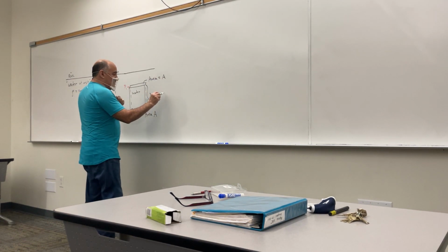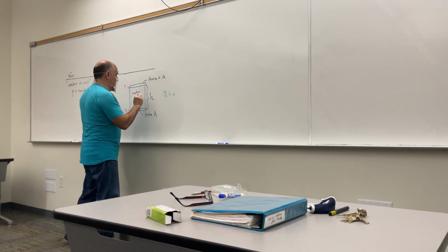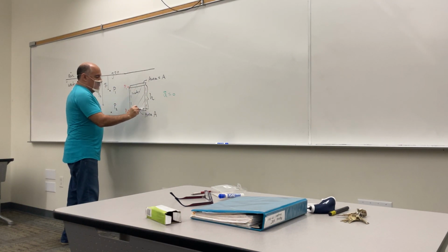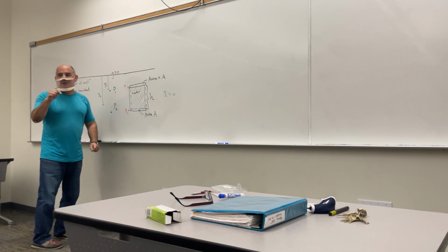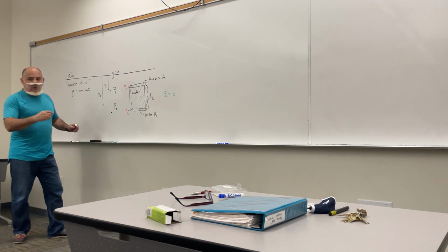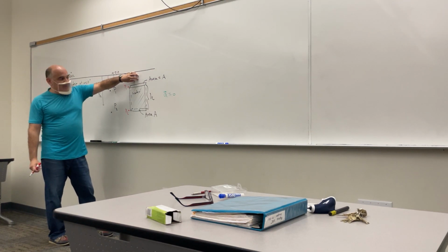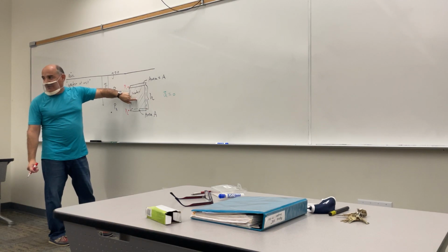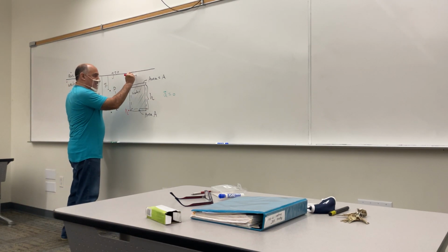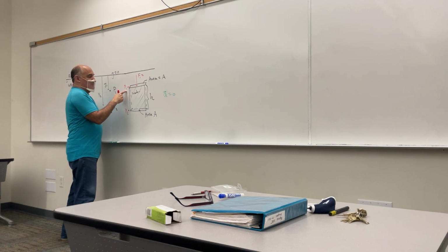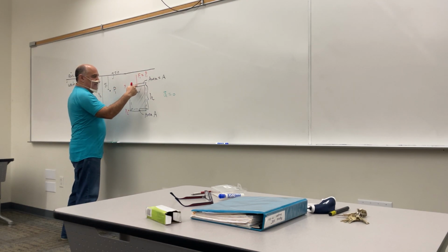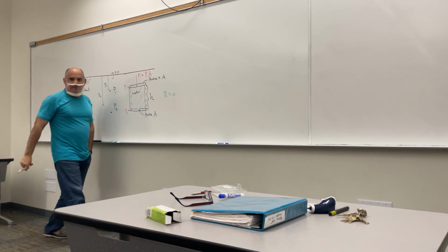And because the acceleration of this water is zero, I'm going to draw the water here that I'm interested in. I want to draw a free body diagram of that water. So what are the forces acting on that water? The water above is pushing down on this body of water with a force that I'm going to call F1, acting at the top of this water. That force is equal to the pressure at that depth, P1, multiplied by the area of that surface, which is A. Agree?